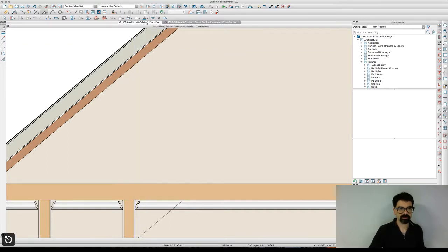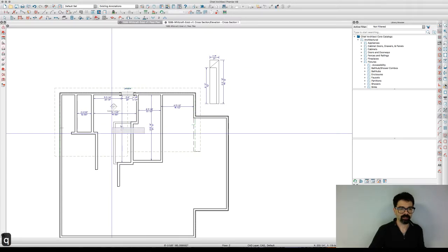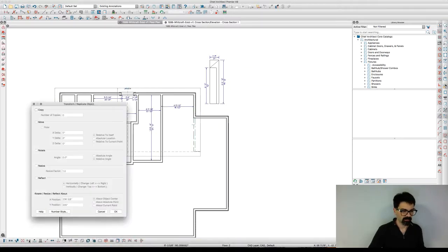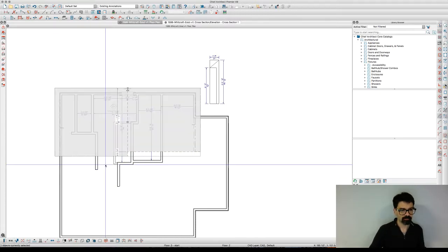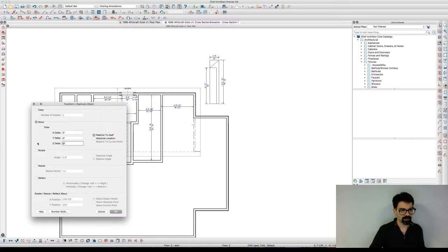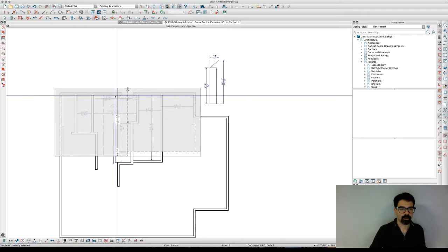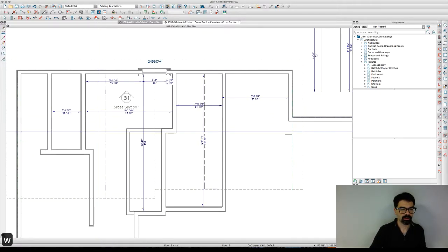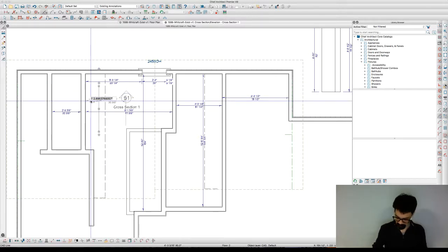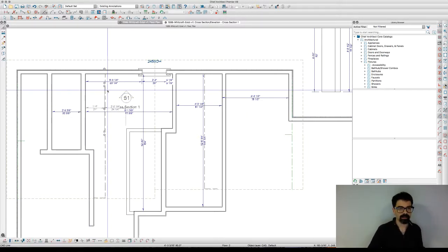So let's go back to plan view, hit Q on my keyboard. I'm going to shift, drag across there, and move, transform, replicate, move in -6'7". Whoops. Transform, replicate again, Z delta because it's going down toward the floor, minus, not star, 6'7". Now, interestingly, let's make that 21 inches. That is pretty doggone close to where that ceiling break line is.